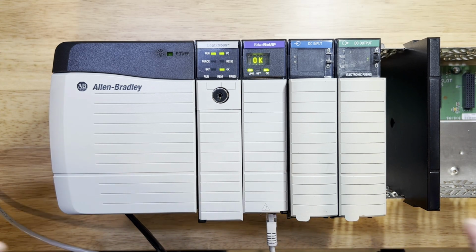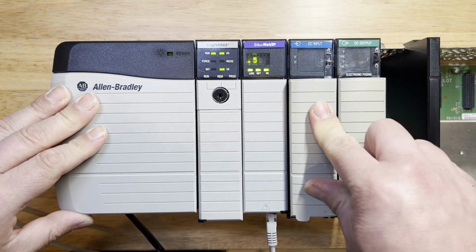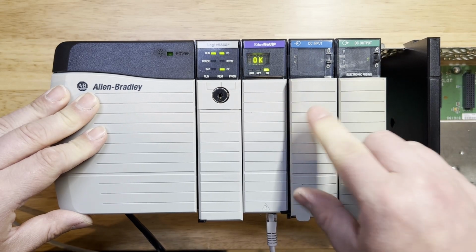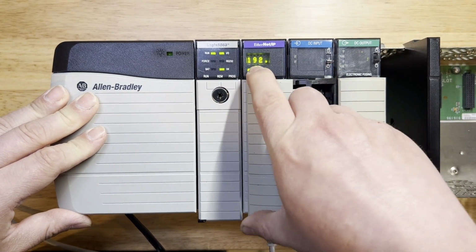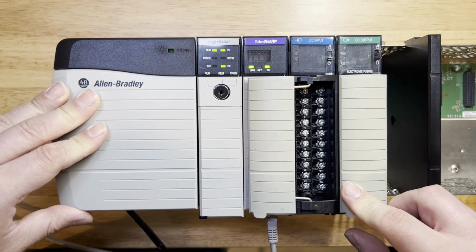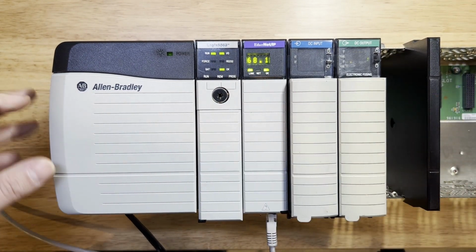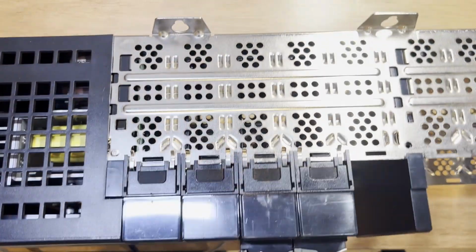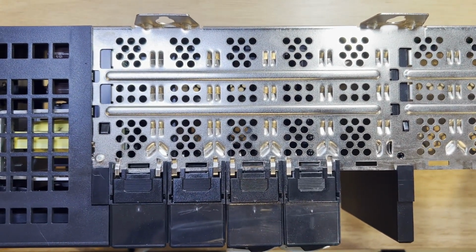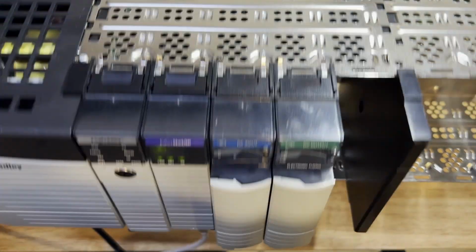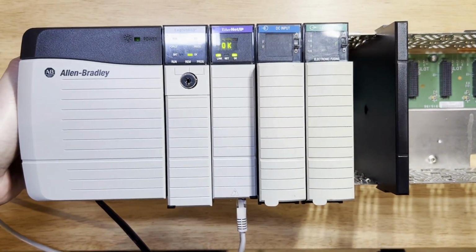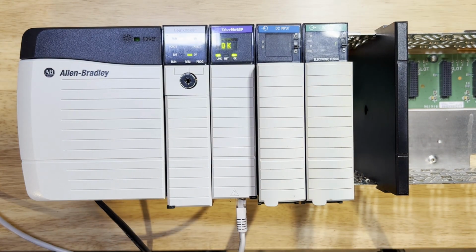You want to make sure you visually check that all of your PLC cards are seated within the rack. Make sure that all the wiring is tight and neatly organized. Also check the top of the rack to make sure there is no debris or metal shavings. Proper ventilation is also a concern. If there is excess heat, it will cause card faults and issues.